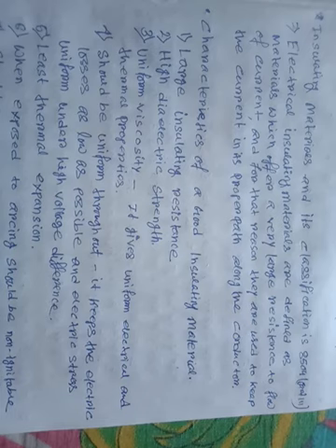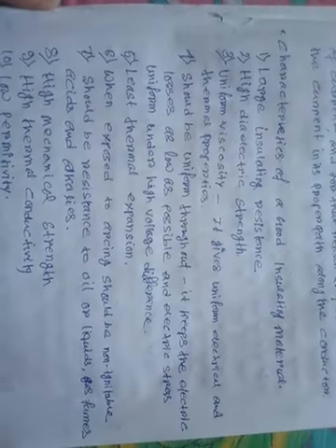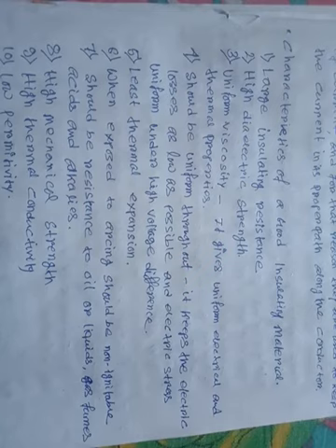Number five, low thermal expansion. Number six, when exposed to arcing, it should be non-ignitable. Number seven, it should be resistant to oil, liquid or gas forms, and acid or alkali.